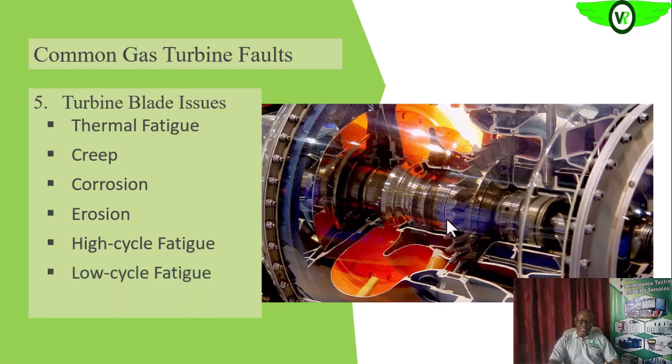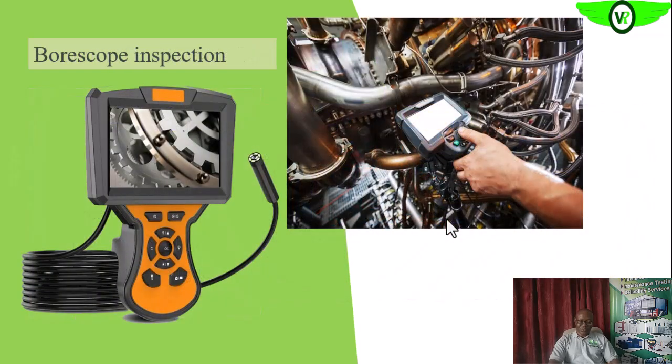Then low cycle fatigue, maybe because you're having too frequent startups on the gas turbine itself. Are we getting it? Too frequent startups can lead to low cycle fatigue. So like we said earlier, the borescope will help us look into the turbine to see the blade and see what is happening with the turbine blade, even the compressor too.